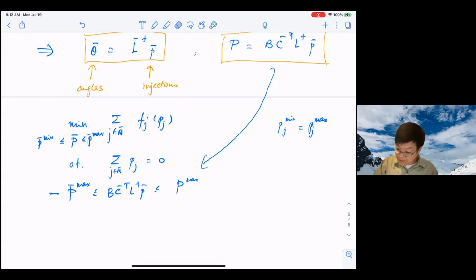So this is a typical formulation of economic dispatch, or sometimes it's called DC power flow, where you want to schedule generations subject to two or three sets of constraints. One is the capacity constraint, which is this. One is power balance, and one is the line flow. You can include other constraints as well. They're all linear, and therefore they can be solved easily, by linear programming.